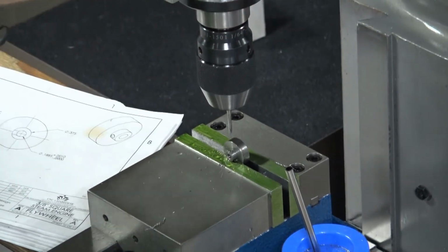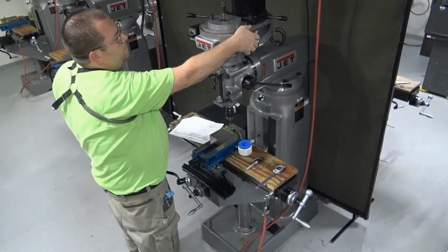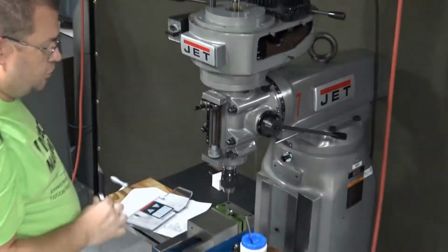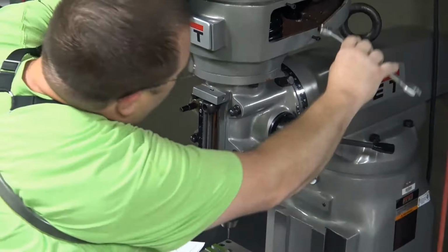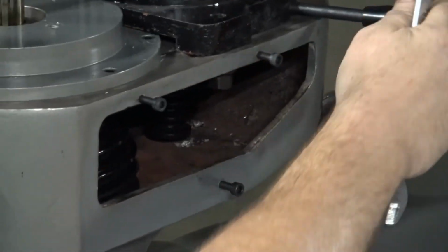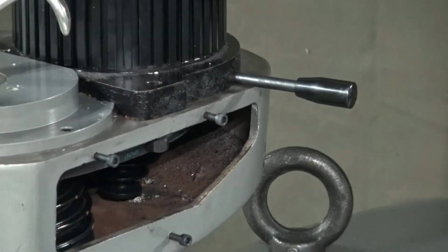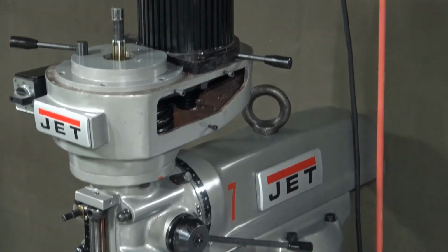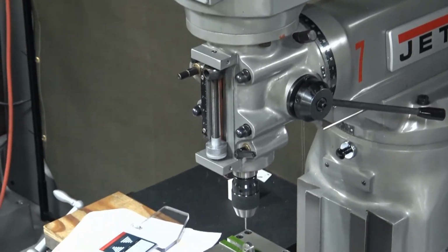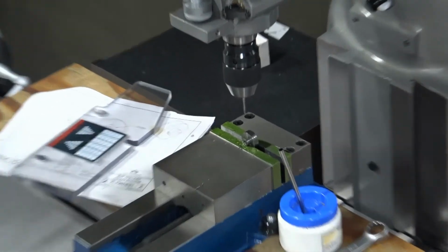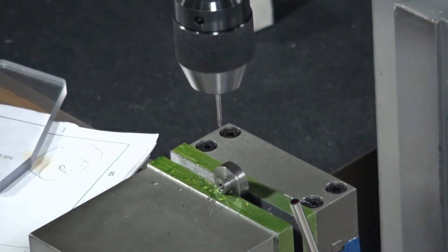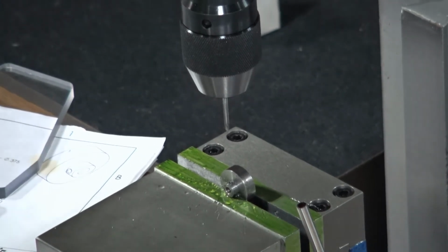I believe we said during the lecture portion that one thing you can do to keep from applying too much pressure is loosen the motor up and just put slack in that belt. So now the only thing that I'm turning is the spindle itself. I'm not actually turning the belt and the motor and everything with it. So my cutting forces should be down, or what feels to be cutting forces. Some of it's just drag.